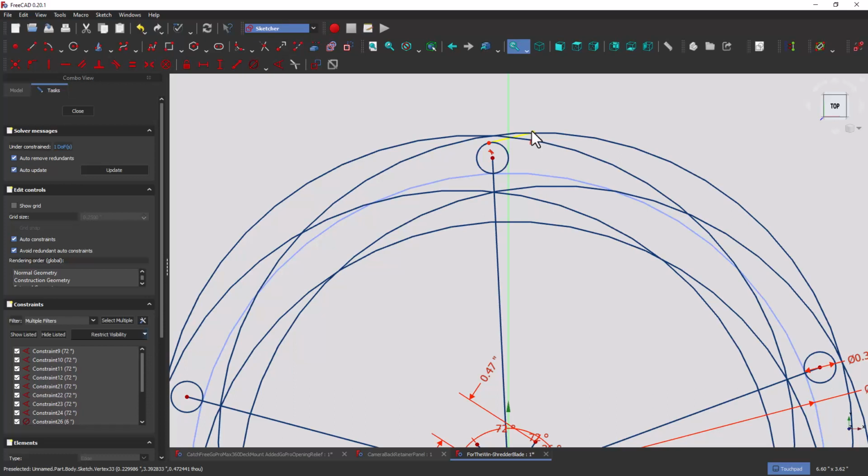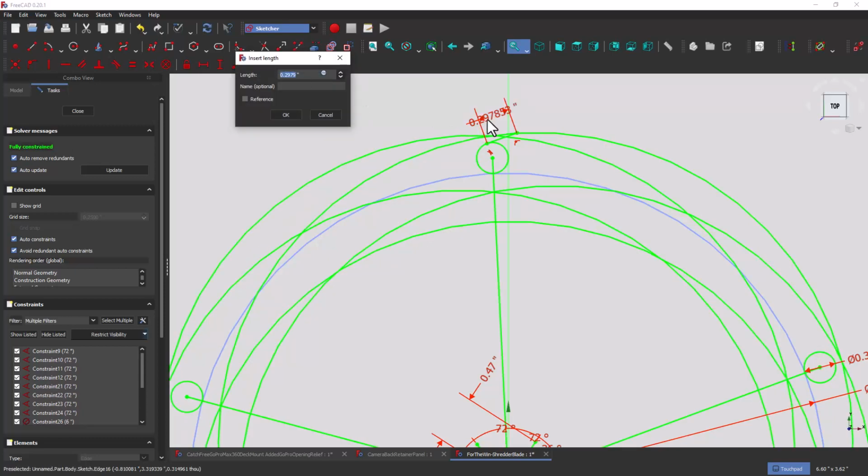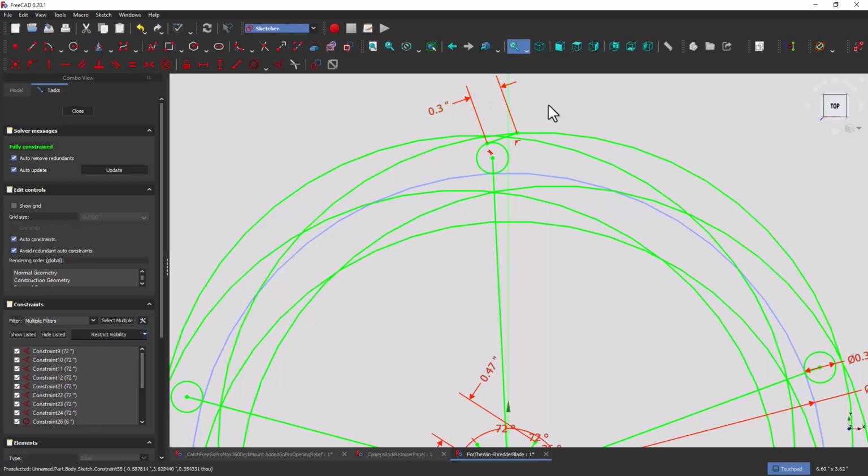And I'm not sure, but maybe it was more like something like that, okay? And what I'm going to do is lock that, whatever the length is the one I want. So I'm going to go in here and give it a dimension, and it's telling me it is, let's go again with 0.3. It's very close to 0.3, 0.978. All right. And the reason I do that again is just to give us some round numbers. It doesn't have 4 digits of some strange relationship there.